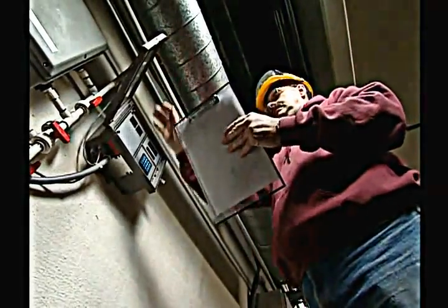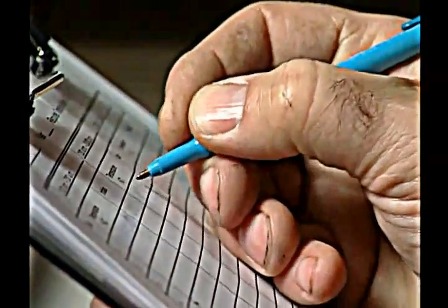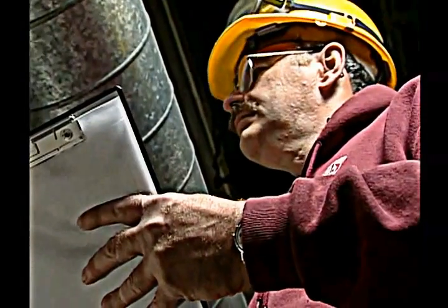If we know that there's turbidity in the water, we know that there's particulates in there. We don't know what those particulates are, but we know that some of those particulates could cause health problems. And so throughout our history as water suppliers, we've been measuring turbidity because it just gives us a general idea of the cleanliness of the water.